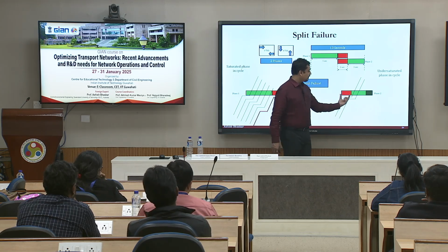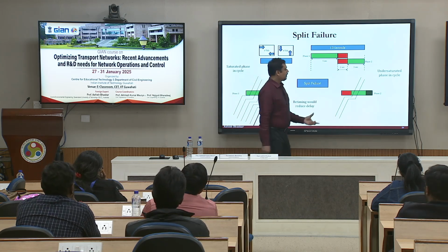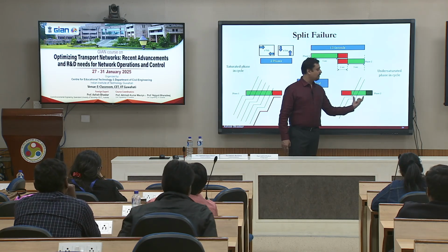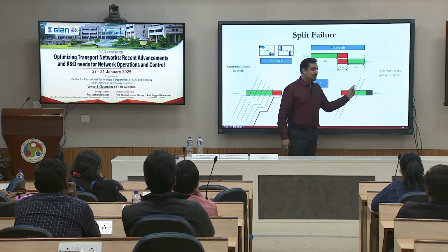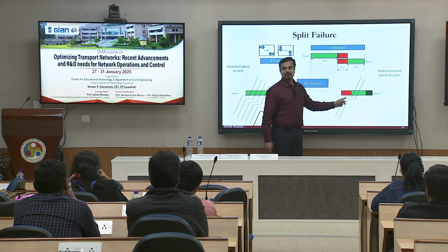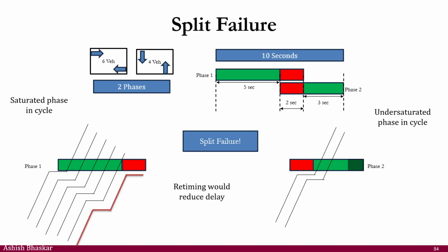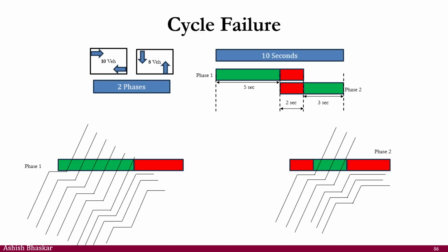Yeah. So, I forgot to mention this is a stop line loop detector, detecting the stop line. In this period what you are saying is you will have one pulse, another pulse, no pulse, right. What about here? All pulse, 100% occupied more or less in this figure. What about here? No pulse, not occupied. So, if you look at this green and red together, you have almost 0 occupancy for the initial red, in fact 0 occupancy, and some occupancy in the green. That is an interesting thing again.